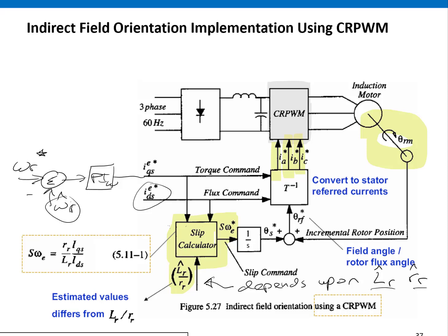One of the things, these are tough, but for example, the rotor resistance is sensitive to temperature. So one of the challenges with implementing this was the fact that you needed to have some kind of model reference adaptive controller or something. And this is an opportunity, I think, for, say, machine learning and things like that, too. Instead of using those old techniques, we've got better techniques. We've got data that we can use to improve our model, let's say, based on features that we can extract from what we measure. It's just a little bit of an aside. But that's a sensitivity that you have.